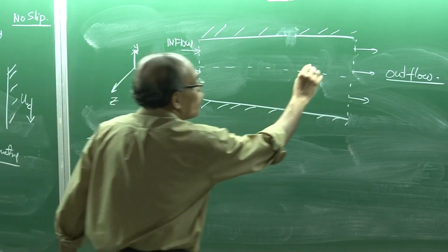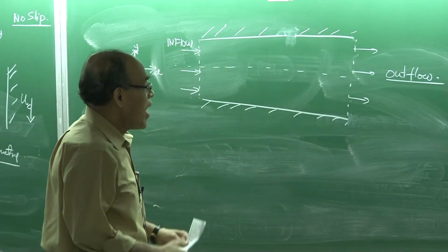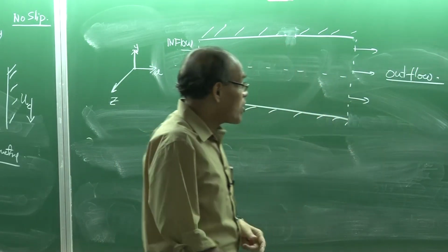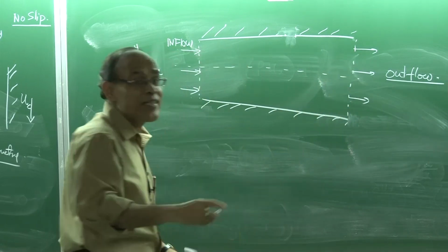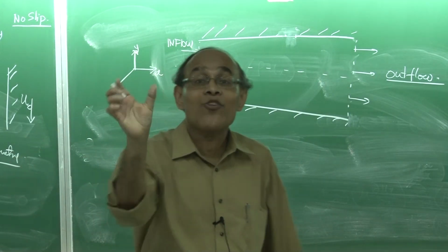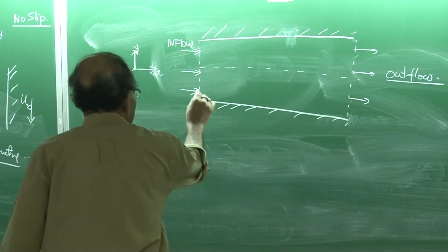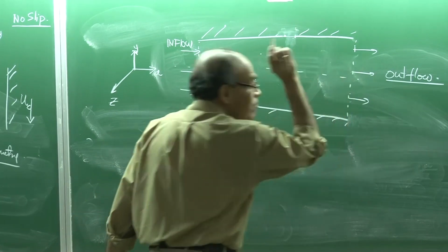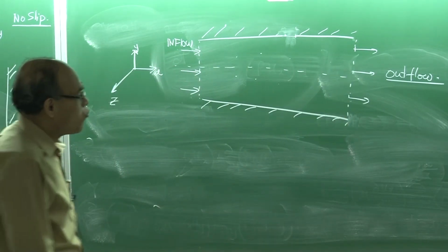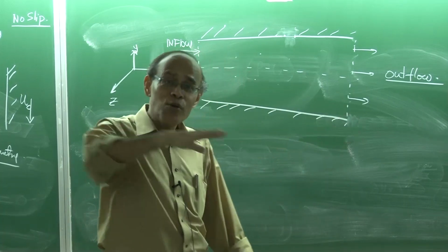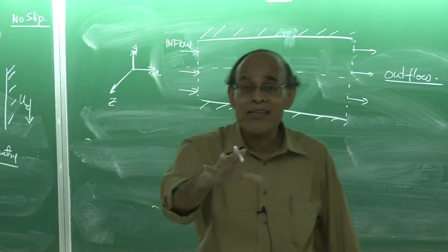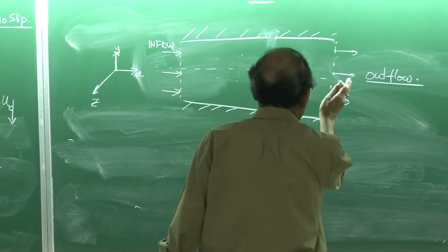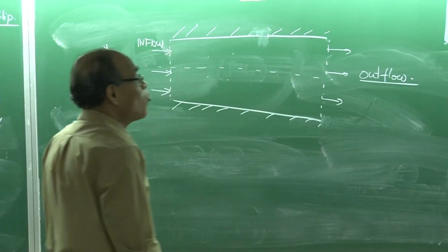that is, there is no backflow because the fluid does not really enter into the system. And since it is one-dimensional flow, one-dimensional flow is essentially assumed at the outflow, and that means we will retain the first order derivative and drop the second order derivative. Everywhere the second order derivatives on momentum velocity components are going to be applicable, but at the outflow boundary, we will assume that the flow is predominantly unidimensional, which essentially means that space is now behaving like a one-dimensional coordinate. You can go from left to right, but you really cannot come back. There is no flow reversal in the system.